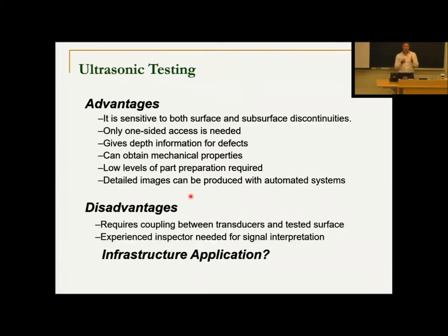Recall the coupling. We have to be able to attach the transducer very well. So for a very rough surface or a dirty surface, it can be difficult to get the energy in. And you need that physical contact, so that's a somewhat slow process. It's not a rapid scan without touching. You have to physically touch here, collect data, and then maybe touch at another position. And these data can be difficult to interpret. You need experience. A licensed and experienced inspector has years of experience, understands the physics, and can interpret the signal to size it.